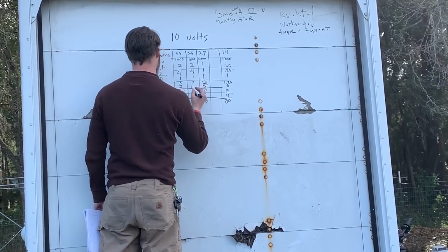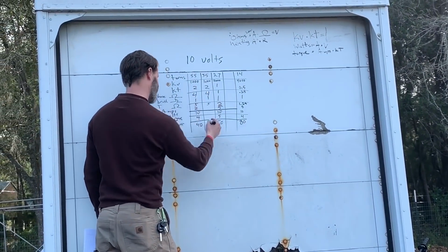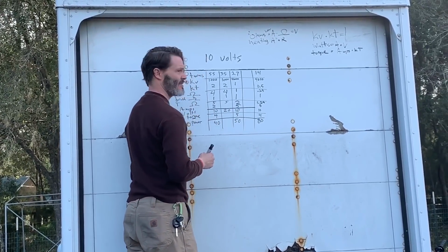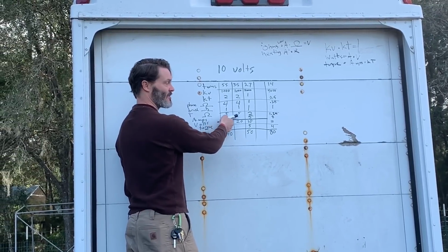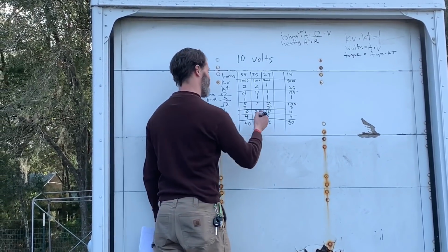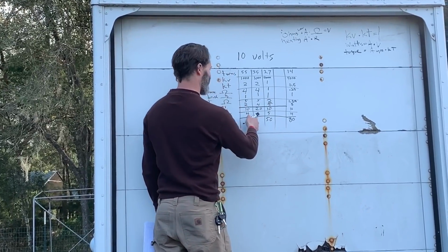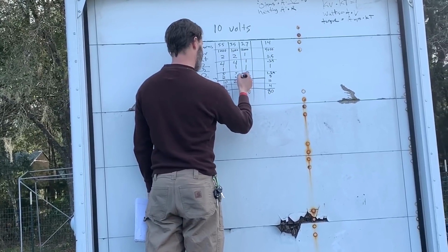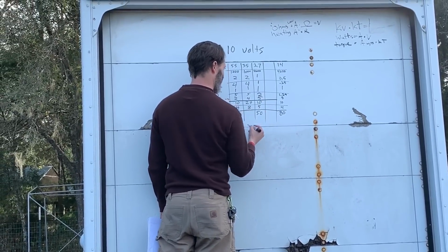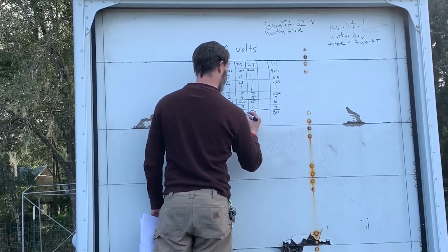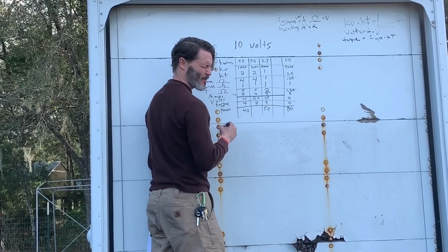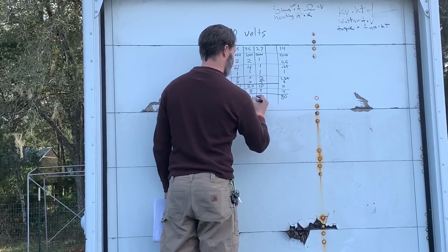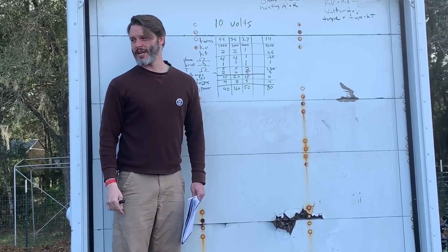They're still 5 ohms. Our amps now, we have 20 volts that we're applying to it, divided by 5 ohms. What would that be? And we can look over here and cheat. It was at 2 amps. We doubled the voltage. It's going to go to 4 amps. Double our amperage. Now our torque, we have the amp units multiplied by our torque units. So 4 times 2. Hey, look at that. We doubled our torque. And we are at, let's see, 8 times 20. What's 8 times 20, y'all? 160. Our power went up 4 times.